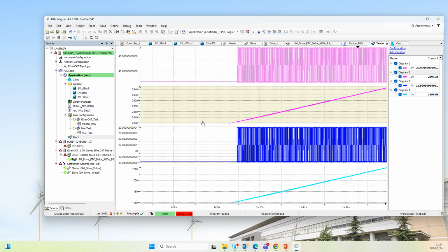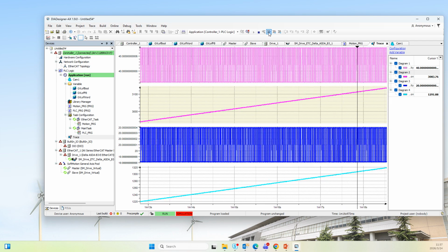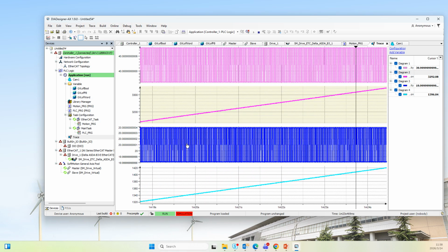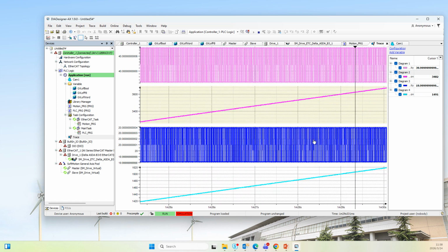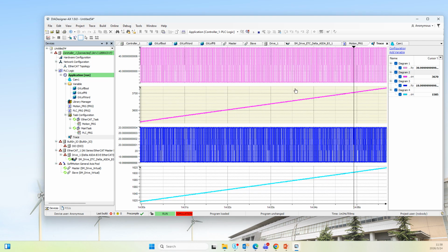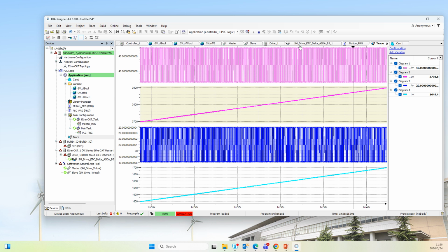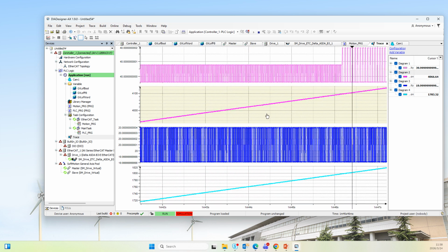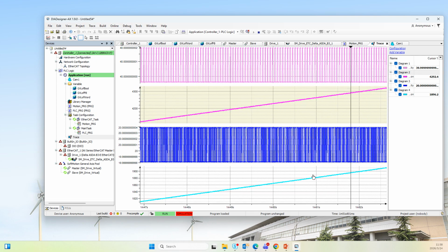Currently the speed of the slave is still 20 and the master is 40, and if you enable this, you can see that the weird thing is the slave is not reduced from 20 centimeters per second to 0, because the function of MC gear out just cuts off the relationship between the master and the slave, but it will not let the slave reduce to 0 automatically.